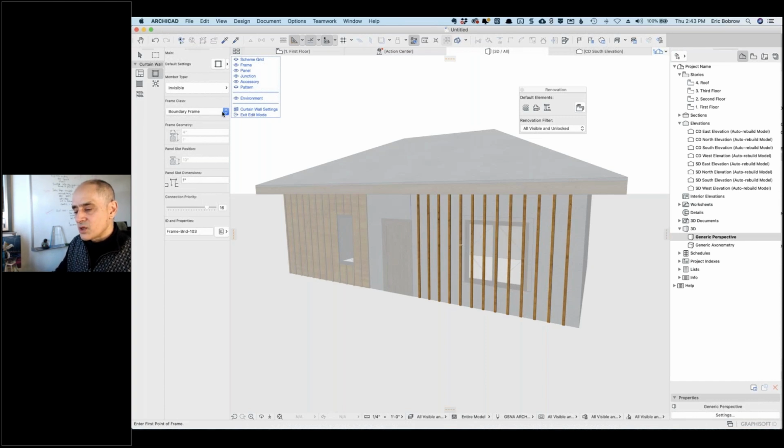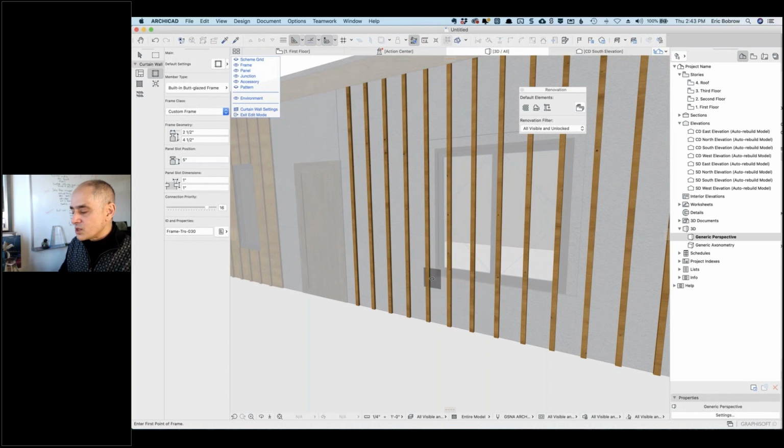And this, it's going to be a mullion, no, it's going to be a transom frame. It's going to go horizontally here. And I'm going to make this have a higher priority. So priorities mean that when things meet, a vertical and a horizontal meet, which one pushes through? And I'll just make this a higher priority. Now I haven't done this much here, so hopefully I'll get this to work, but let's just go from here. And I'll take it over to this point.